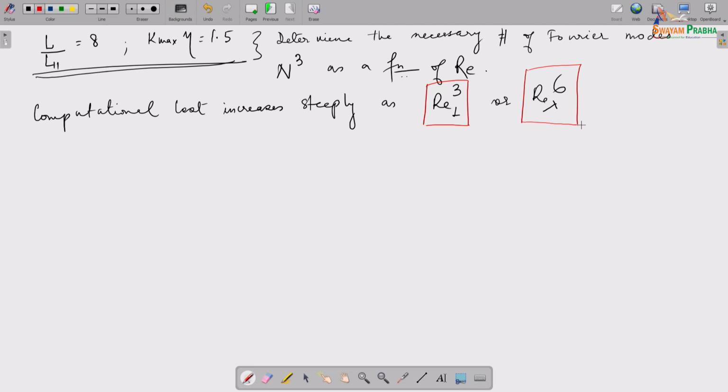You see, the more small scale or microscale motions that you need to resolve, the Reynolds number is going to go up, right. So, that is why, like I had said at the beginning, it is almost impossible with gigaflop computers to go beyond an RE lambda of say 100. Okay. So, I do not have a sufficient computer to do that, okay, right.